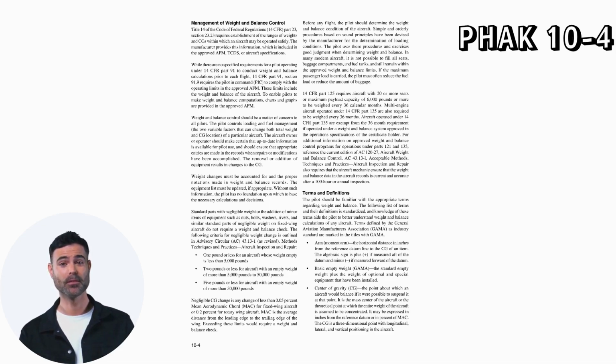Arm (moment arm). The horizontal distance in inches from the reference datum line to the CG of an item. The algebraic sign is plus if measured aft of the datum and minus if measured forward of the datum. Basic empty weight (GAMA). The standard empty weight plus the weight of optional and special equipment that have been installed.